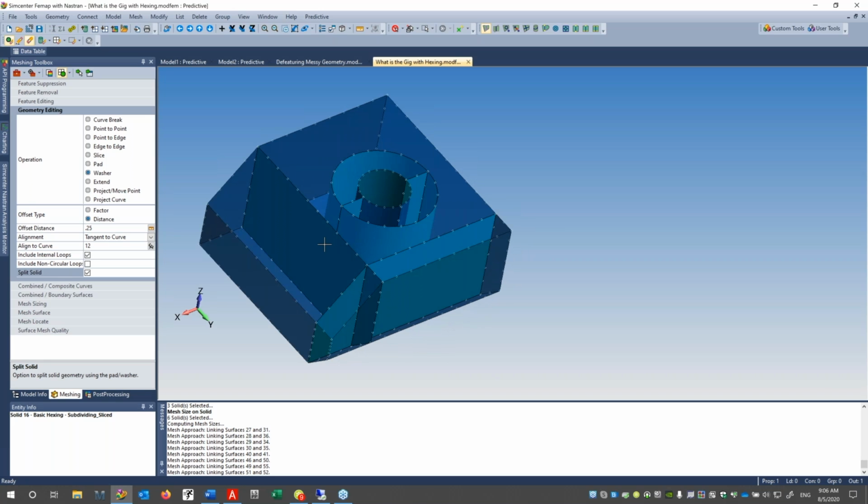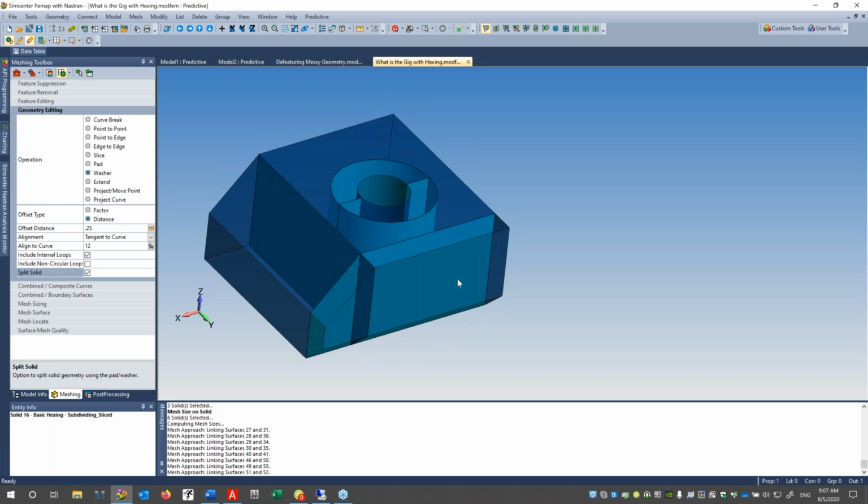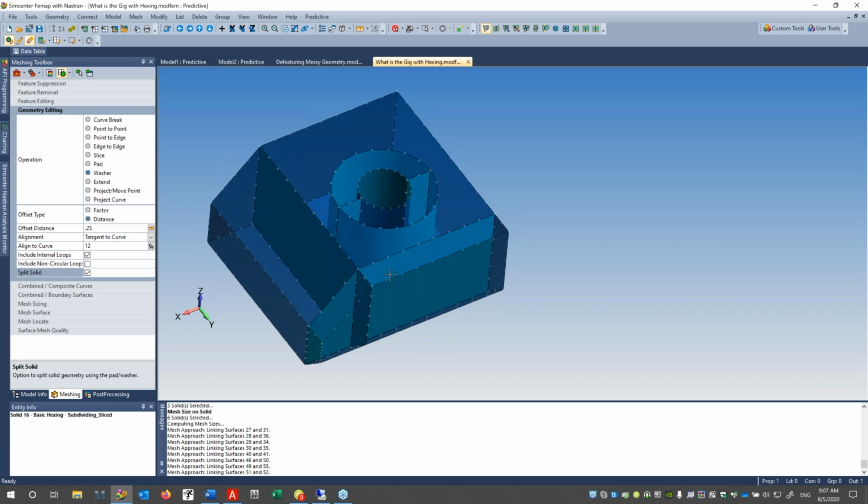There's no easy lunch. What it's doing is it meshes one surface as a master, and then it uses that mesh surface on the next solid. And it's just a way to link meshes up so that you don't have gaps. You don't have holes in your mesh. And on hexing, it links it sideways, upways, things, and there's a nice little section of the manual how it